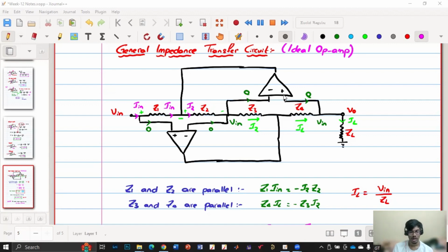We are just trying to show that it can be used and it will work, because we also have this gyrator experiment in our second year UG lab, where we connect only a resistor and a capacitor and show that it works like an inductor. So we'll see the phase difference between input voltage and input current, that 90 degrees phase shift. So it is just an application.